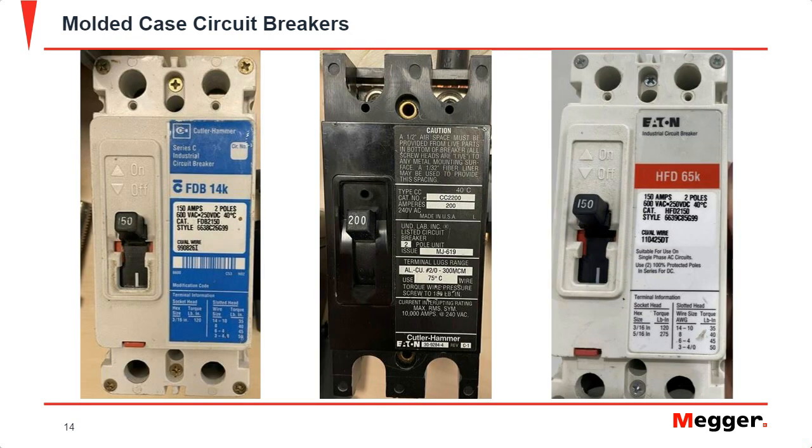So now taking a look at the molded case breakers. Typically with these, you always want to look at the nameplate when looking at the rating of the breaker. So again, the nameplate highlights what the rating of the breaker is, as well as the breaker terminals here. Breaker terminals, again, is where you're making your connection with whatever primary injection test set you're using, or if you're performing other tests on the breaker.